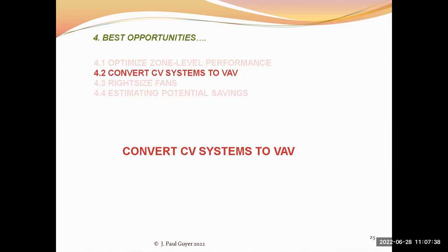And the digital control system will add up that new total quantity of air that's required by the fan, and will speed the fan up and provide the quantity of air that is demanded by all of the zones.